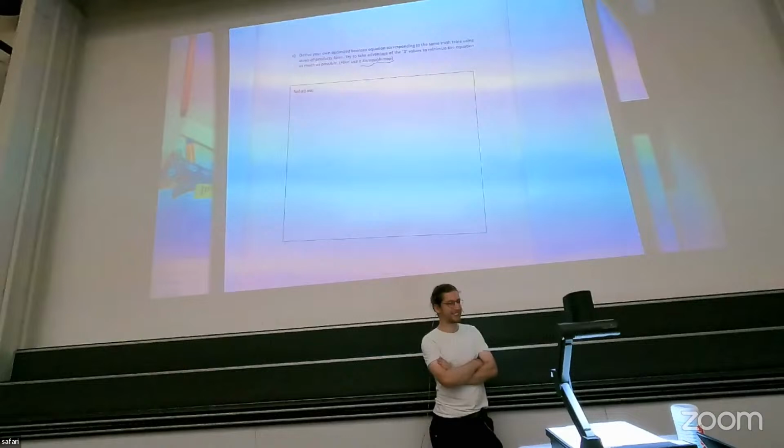Nothing actually, if you think about it, but if you construct it out of gates, ORing is a simpler operation than adding, because in the add there is a long 32-bit carry chain. In the OR there is no such delay. It comes from back in the good old times when we drew circuits by hand, we didn't have cell phones, we cared about optimizing these things, and glaciers weren't melting. But you are right, it could be done in a number of different ways. It's just a convention because, operation-wise, it's simpler than adding.